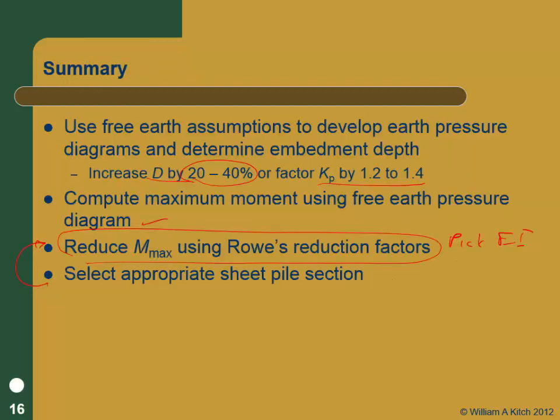So that's the free earth method. What we're doing there is making our statically indeterminate problem a statically determinate problem by assuming we get rigid movement in the pile, and we're ignoring any soil structure interaction.